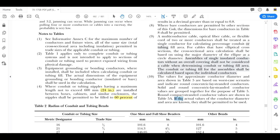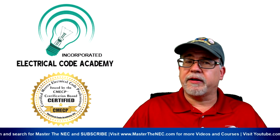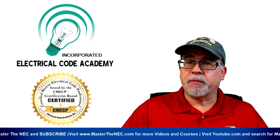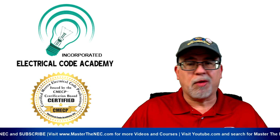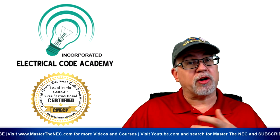The last line here is critical because all of us manufacturers vary our productions. So it says, if the actual values of the conductors' diameters and area are known, then they shall be permitted to be used. So again, long story short, most of us are going to just tell you to use the values that are in Chapter 9, Table 5. But if for some reason we produce a product that has maybe a smaller area, we still have to meet the circular mils for that conductor's required size.